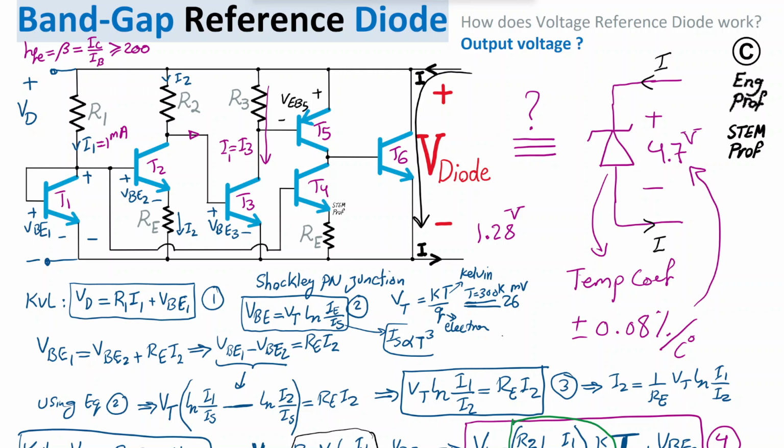So since the base of T6 is connected to a collector, it gives T6 the degree of freedom to have a slightly varying base emitter PN junction, so that when different currents are passing through this transistor, there is no problem for the voltage and current.